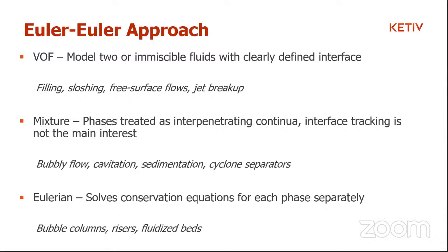If you were looking at a mixing tank problem or a tank filling problem, and you want to understand how the interface behaves over a period of time, then you would choose the volume of fluid model. In this case, only one set of equations is solved for all the different phases in your computational domain. So a single set of conservation equations is solved.